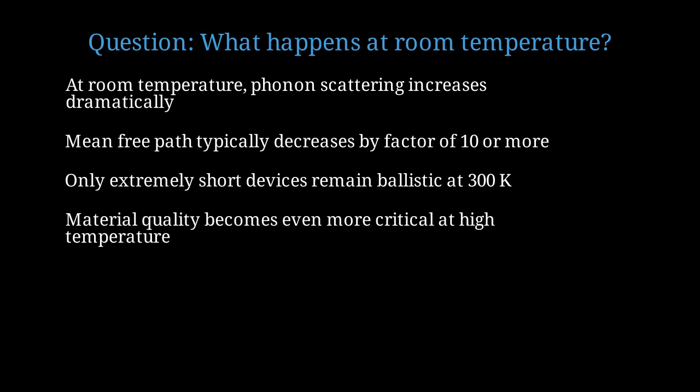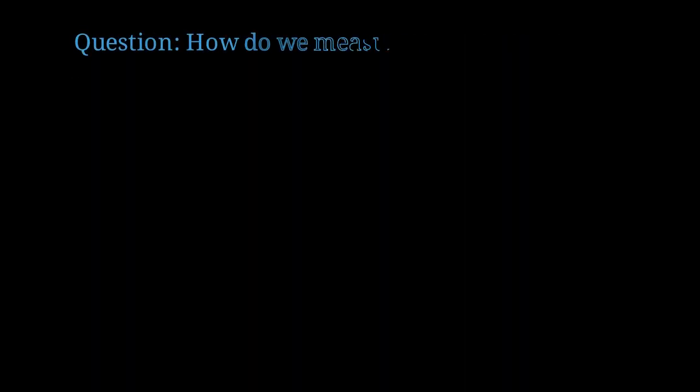Material quality becomes even more critical at high temperature. Any additional impurity scattering or boundary scattering compounds with the phonon scattering, further degrading transport. Another key question: how do we experimentally measure and verify ballistic transport?